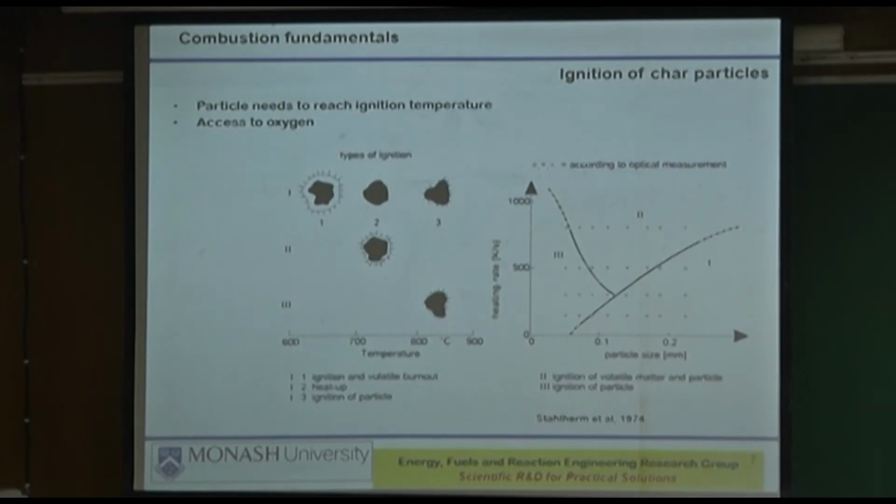That raises the temperature as well near the vicinity of the particle, which then gets heated up as a consequence, and the particle then ignites. So these are the three steps shown in here. As they ignite, the volatiles combust, then the char remains, more volatiles released, that then the char then gets combusted, and essentially it loses its carbon content as much as possible before converting, remaining only with ash and nothing else, hopefully.